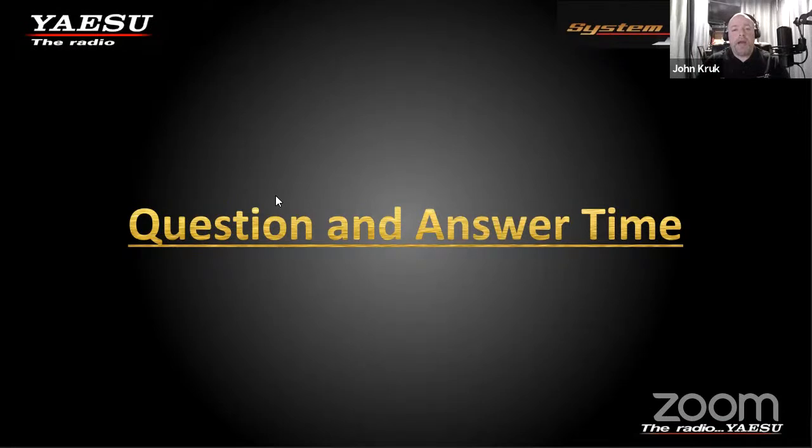If your call sign is embedded, it is. Mind you, Fusion is an amateur protocol, so it actually allows you to enter your call sign. Once again, it's not an ID or something like that; it's your actual call sign, so it does go out. The reason I say that is because if you are in a room that has analog users, your ID is not going to come out there. And if you're doing some of this cross-moding to other digital modes like DMR, P25, and NXDN, those are all numerical, so your ID does not cross over. The FCC does not consider that a legal identification.